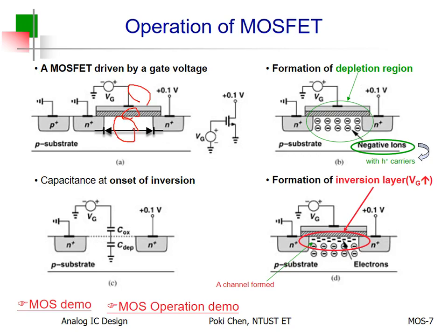And the body, such kind of capacitor structure will help you because as the capacitor, we have Q equals CV. The capacitor means here, I mean the structure here. So usually we have C oxide. Later I will explain. Anyway, Q equals CV. What does it mean? The more voltage you apply, the more charges will be stored into the capacitor, but to both sides, right? Not only one side, but two sides.